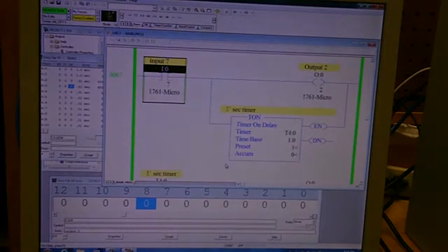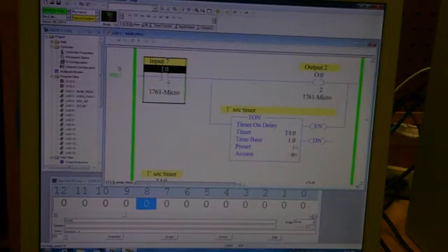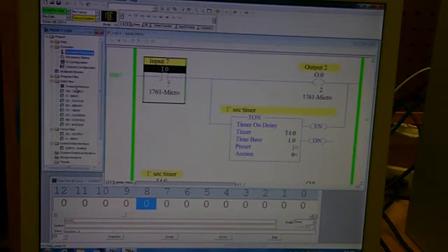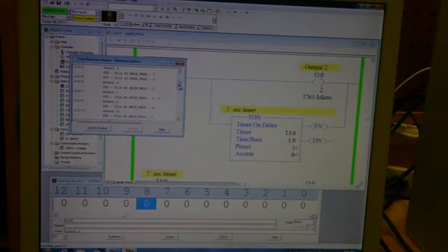Notice that output 7 came on that time, but output 7 did not come on the time before. Now, why is this? Something's linked between them, because the rule says that for my output, it can only be in one run. I have output 7 in 2 runs, in run 4 and 9. The program is a sequential program.